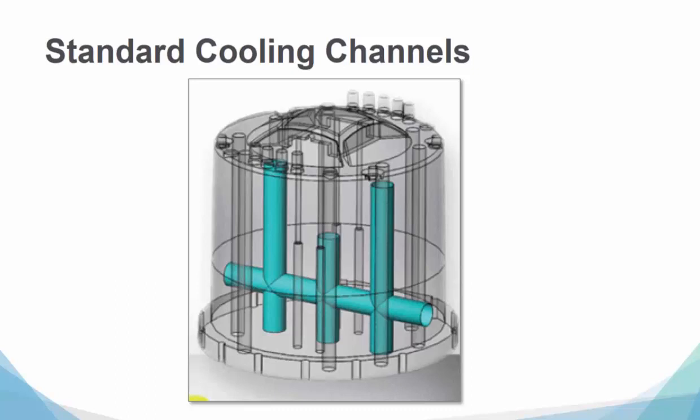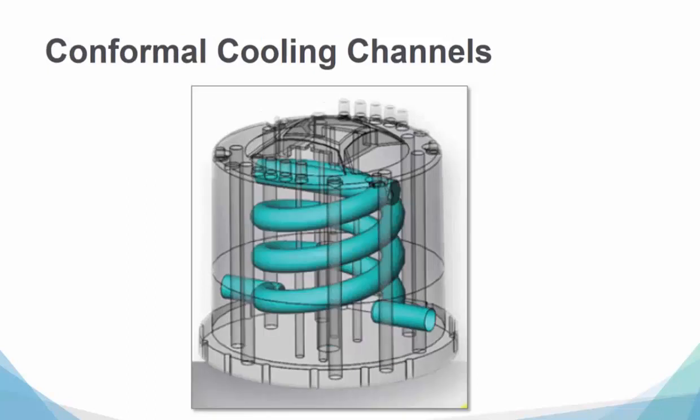It goes toward the beefy areas where there's steel, but doesn't so much follow the shape that you see, which is the cylinder body. Comparing that to what a conformal cooling water line does, here you see there's one inlet and one outlet. It spirals its way up, crosses across the top, spirals its way back down. So its intent is to follow the shape and to capture as much of that shape and depth as it can.